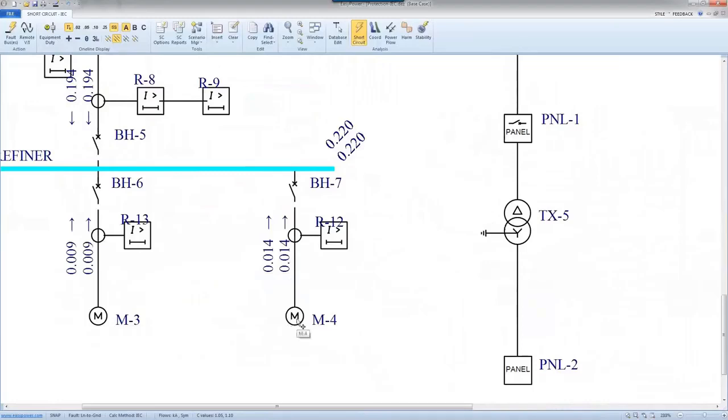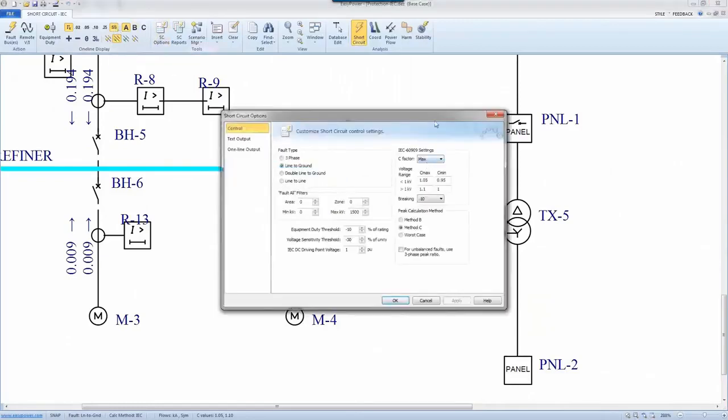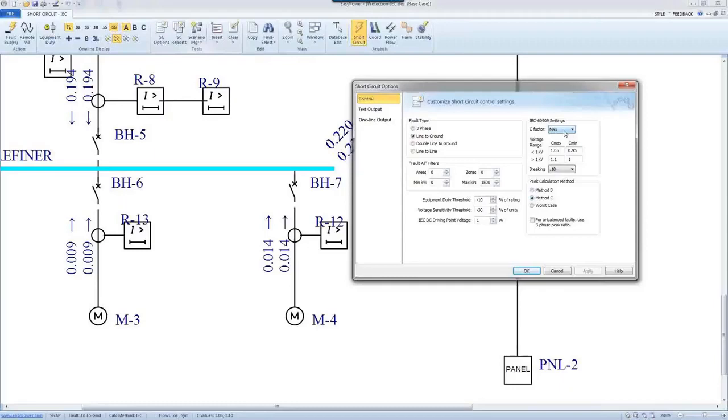So the addition to that statement is that for balanced faults, we cut off motor contribution for a steady state once Cmax is chosen. If you switch to Cmin, and I mentioned it before, you expect to cut off any contribution and try to make the fault current minimum. As part of that approach, we will cut off the motor contribution.